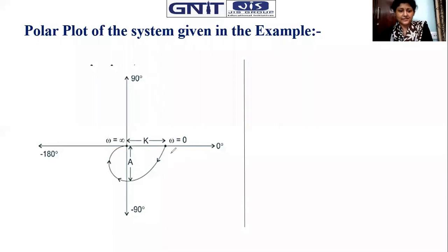That is K at 0 degrees, the polar form with magnitude and phase, and it ends at 0 magnitude with phase angle minus 180 degrees. So K at 0 degrees is the start, it obviously crosses the negative imaginary axis, and then it emerges to the origin, with vector length becoming 0 and angle minus 180 degrees. Very simple. It's a freehand sketch, so you sketch this one.